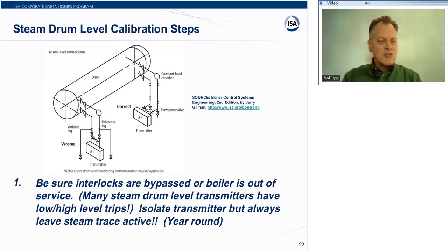And another gotcha is, Hunter had mentioned the steam tracing, and you should leave that active. Mainly you want to have consistency. So the calculations that Hunter just went through, if you turn the steam tracing off, all those numbers go out the window. If you leave the steam tracing in place, it allows you to have consistent testing, and it works 100% of the time.